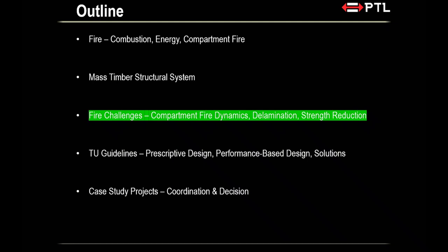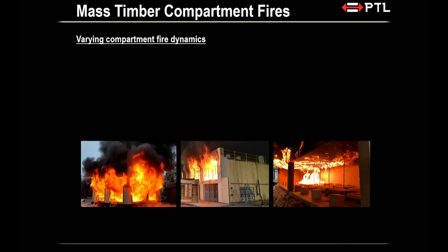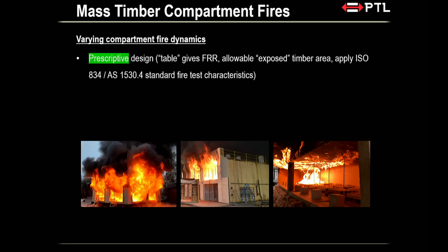Now I'm going to talk a little bit more about my perspective of mass timber fire safety, touching on compartment dynamics, the aspect of delamination, and also strength reduction. So why do I worry about compartment fire dynamics? Well, that's the source of all problems. But sometimes I don't care about fire dynamics, and you will ask me why, because I'm on a completely different pathway. In fire design, there's prescriptive design, and then there's performance-based design. Under prescriptive design, a lot of the time I don't care about the fire dynamics at all. I know it's going to happen, but I just do not care. I'm doing design by prescriptive means.